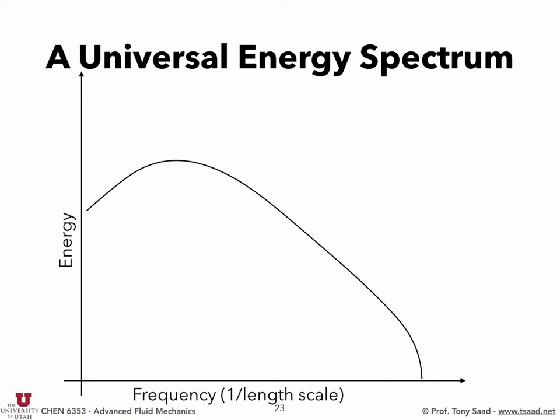You know what? It's not going to do anything. That randomness will dissipate in a single time step calculation. Why? Because the random number generator does not have this energy signature. So turbulence randomness is not random in the sense that you just pick a random number, like a Brownian motion or random walk. No, it is governed. The reason you get this energy signature is because of the Navier-Stokes. This turbulence is governed by the Navier-Stokes.